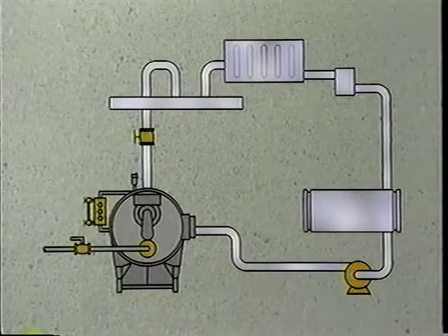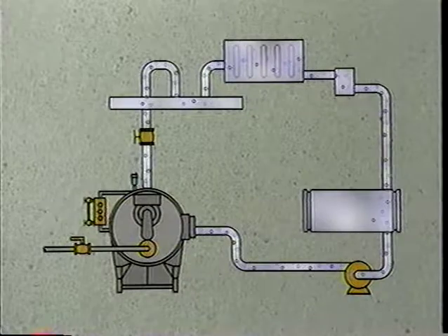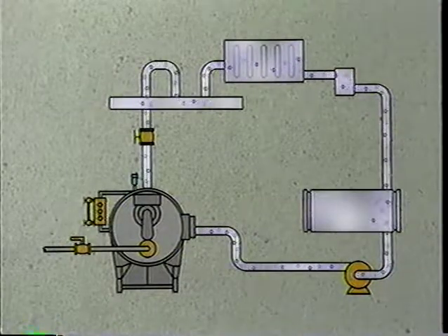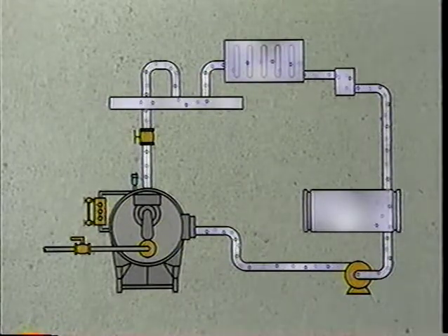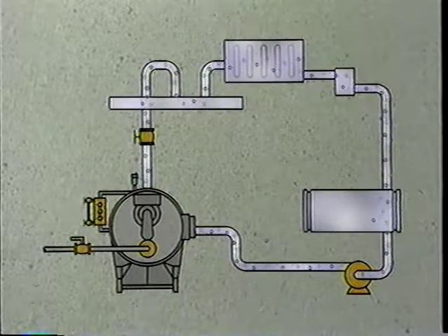Carryover occurs when small water droplets are carried in steam lines. Carryover can result in water hammer. Water hammer is a banging condition caused by hydraulic pressure that can damage equipment.